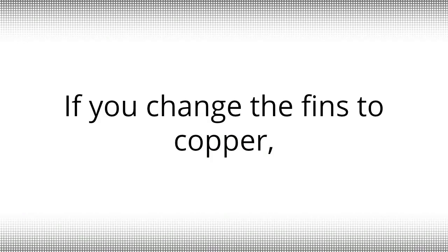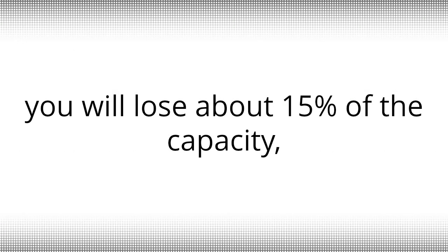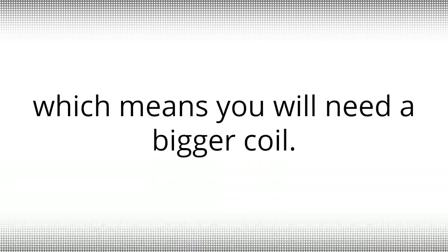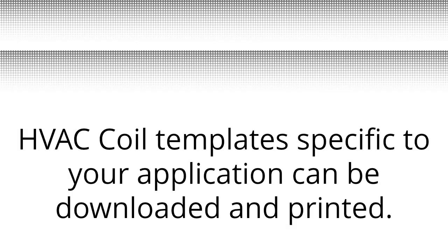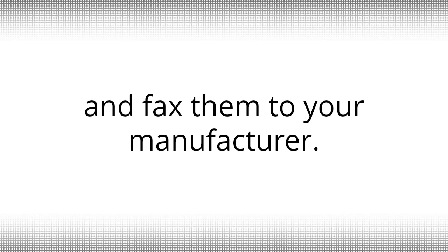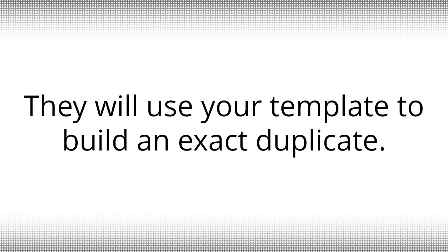If you change the fins to copper, you will lose about 15% of the capacity, which means you will need a bigger coil. HVAC coil templates specific to your application can be downloaded and printed. Bring these templates to your job site, mark them up, and fax them to your manufacturer. They will use your template to build an exact duplicate.